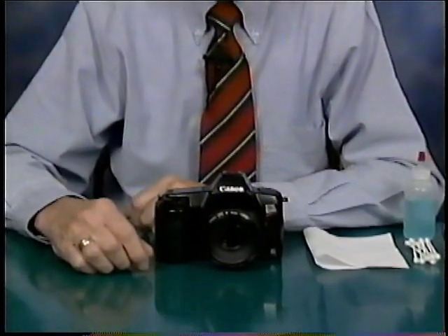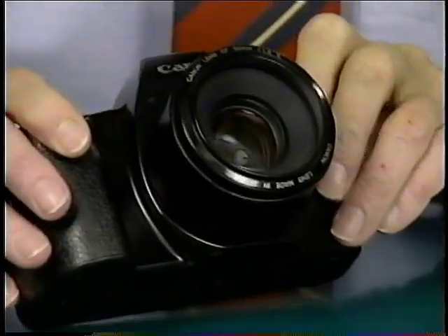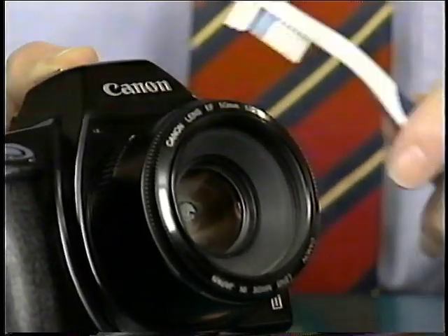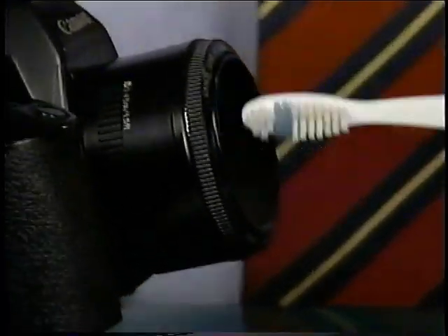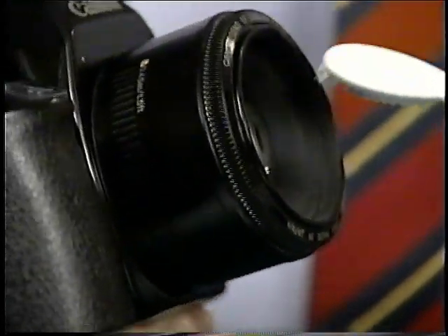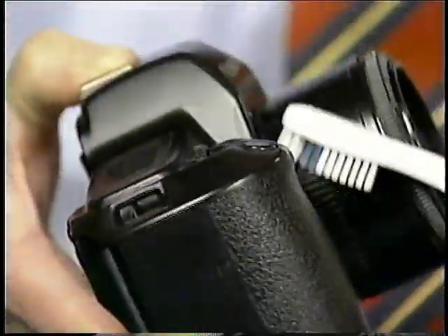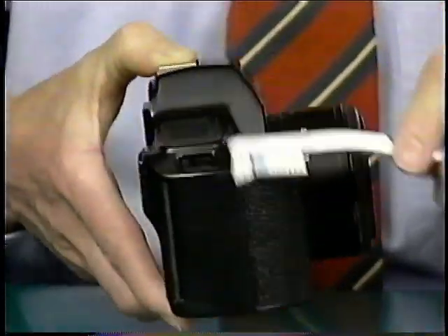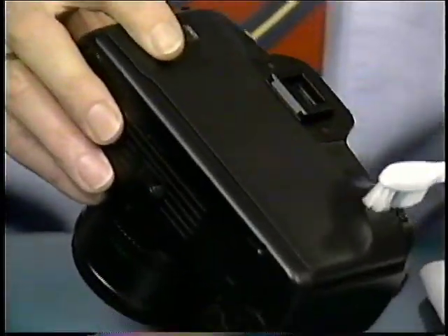Next, we're going to use a single lens reflex camera to demonstrate some of the cleaning you should do. The same would apply to a lens shutter camera as does to a single lens reflex. But the first step is going to be to go over the camera with a stiff brush and take away any dust or sand. And for that, you're going to work inside the lens rings. Don't touch the glass with a stiff brush. Also get along the edges here between the seams where the lens joins the body. Any place there's a seam or a control button where sand or dust can gather, just clean those out.